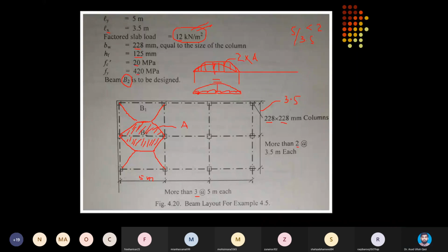So it was done to convert the trapezoids or triangles into equivalent UDLs by using the equivalent widths, so that I can determine the hogging and sagging moments more easily, which are exactly equal to the moments which I would otherwise calculate by solving the beams with trapezoidal or triangular loads.